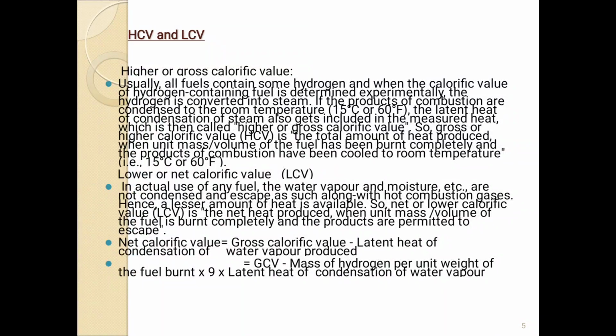Now we'll see what is HCV and LCV. HCV means higher or gross calorific value. Usually all fuels will contain some amount of hydrogen, and when the calorific value of hydrogen containing fuel is determined experimentally, the hydrogen is converted into steam. If the products of combustion are condensed to the room temperature, the latent heat of condensation of steam also gets included in the measured heat, which is then called higher or gross calorific value. So gross or higher calorific value is the total amount of heat produced when unit mass of the fuel has been burned completely and the products of combustion have been cooled to room temperature.